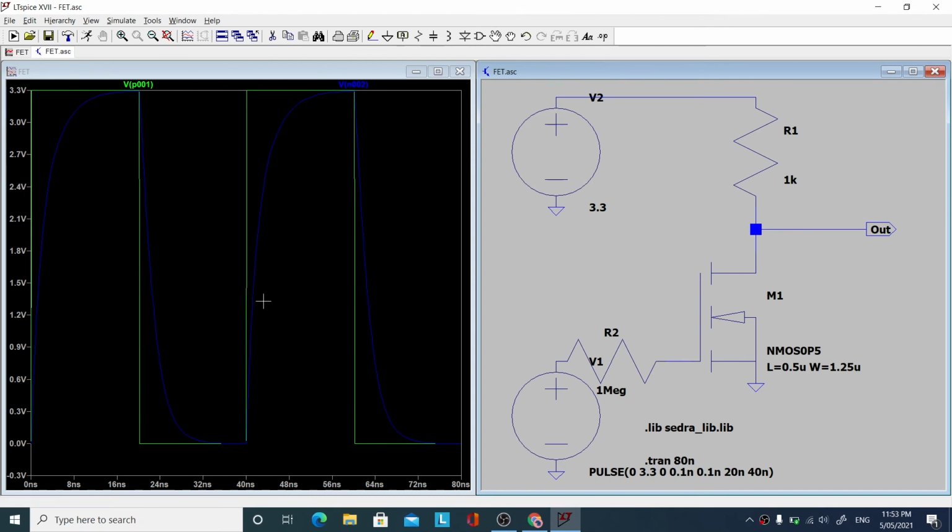The relevance of this is that if we connect two logic gates together, then the output of one logic gate might change from low to high, but it takes time for the input to the next logic gate to register that, because the first gate has to charge up the gate to source junctions of the FETs in the second logic gate. So basically this is the reason why we have got propagation delays and contamination delays. The FET does not immediately react to a change in the input, it slowly charges up. So there's a contamination delay when the FET hasn't really seen the input change, and then there's a propagation delay when the input to the FET has finally reached the value at the output of the previous gate.